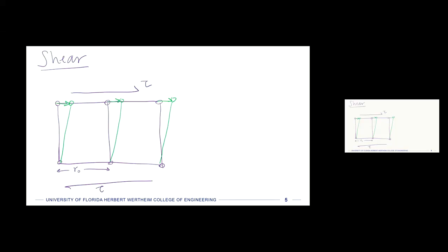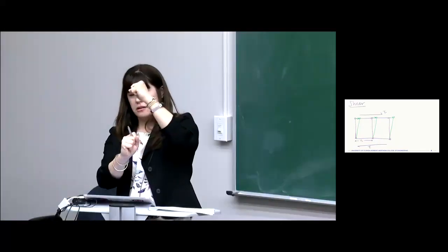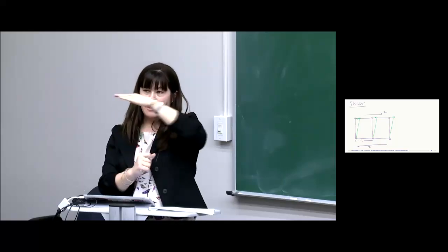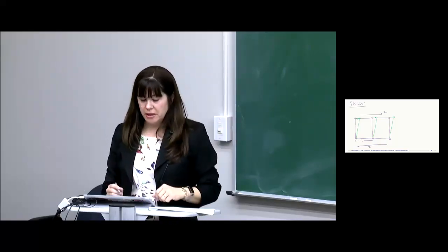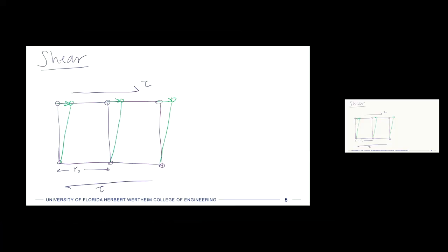But if we keep going, right, we keep shearing this thing long enough, these are really not tethered. The lines that I've drawn, they're imaginary, right? Really, there are electron clouds, and these atoms are relatively fixed in space with relationship to each other. So if I keep shearing it, I'm going to stretch the distance just a little bit between the atoms on that top layer and on the bottom layer. And if I keep going and I keep stretching, I'm going to eventually get those atoms on the top not close to where they were, but actually closer to where the next atom started, right?